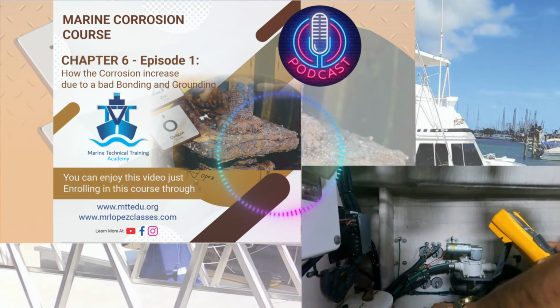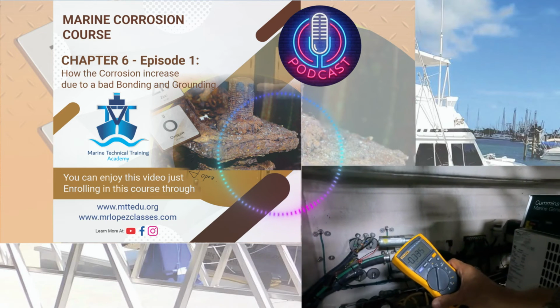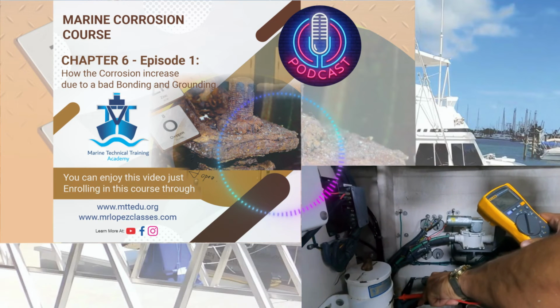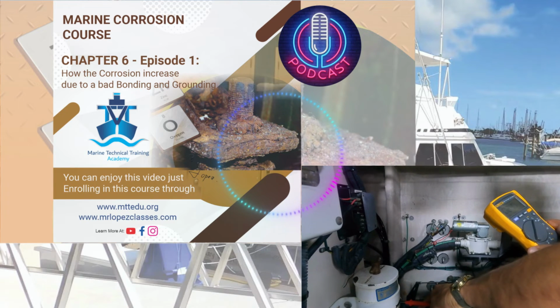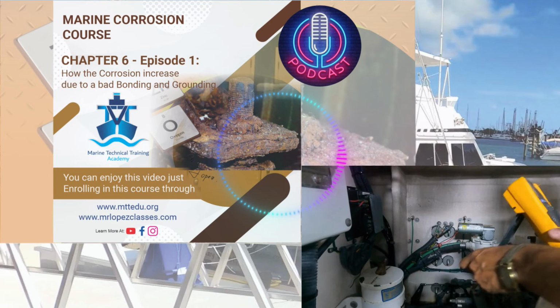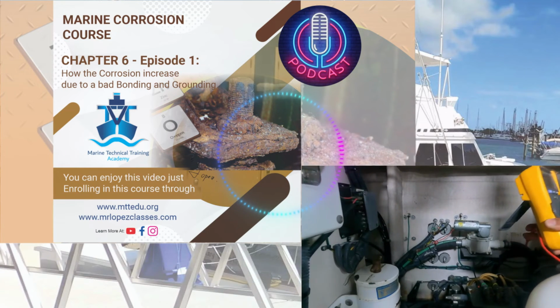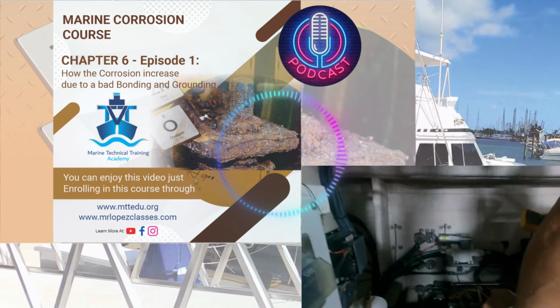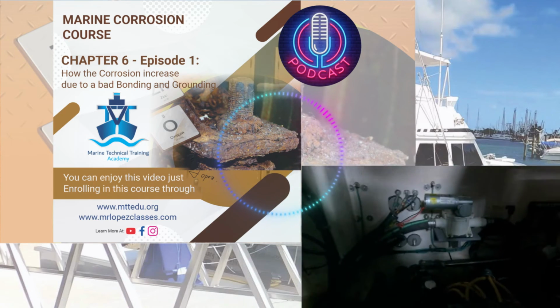Where is the galvanic isolator located? The galvanic isolator is inserted in series into the ground line. The ground is cut and you insert the galvanic isolator in between, in series. What is the function of the galvanic isolator? Block the intrusion of bad currents inside of the boat.